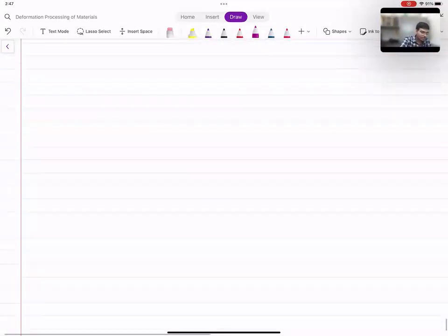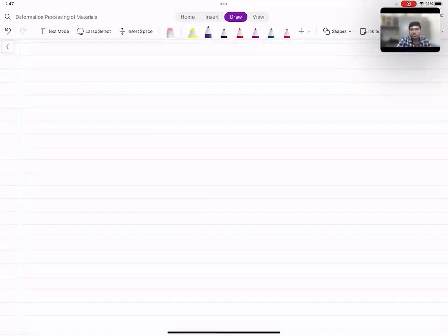Okay, so basically what happens is, when about 2/3 of the billet has been extruded, the surface which is in contact with the container starts to pass through the orifice and go into the extruded portion, and the portion which was in contact with the surface of the container generally gets oxidized, or there is formation of oxide layers over there. Okay.